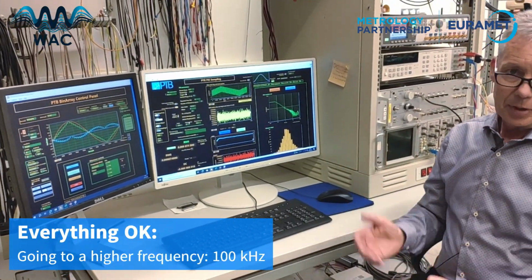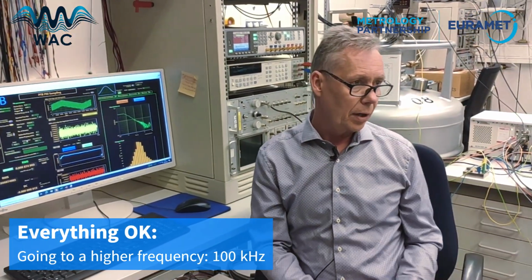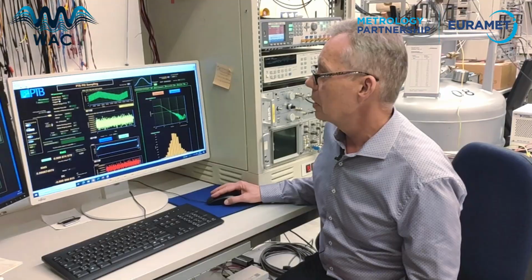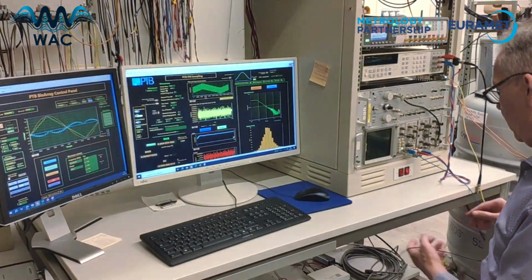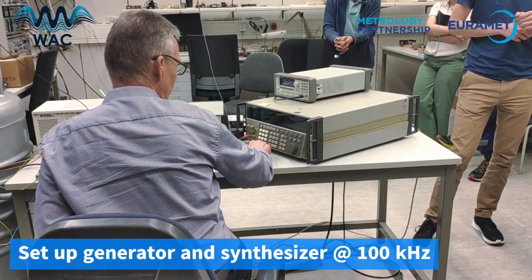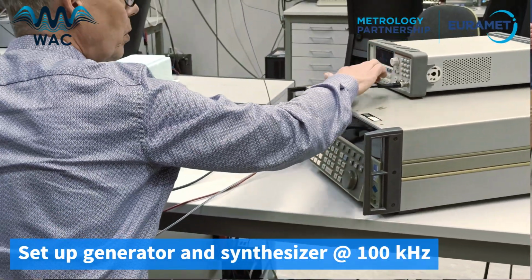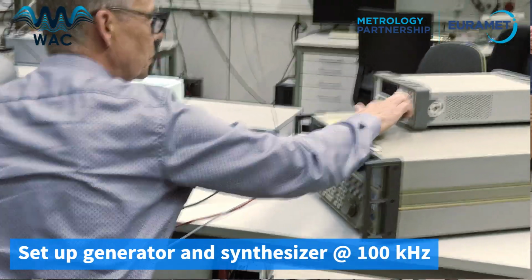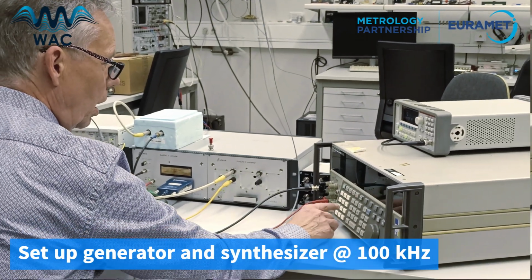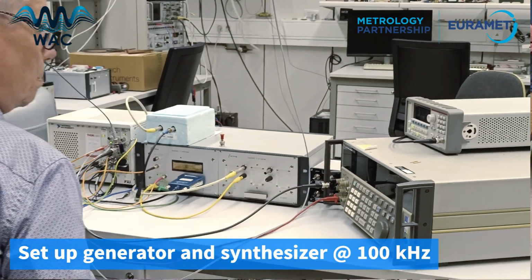Once this is set up, it's very easy now to go to a higher frequency. I just have to reprogram the calibrator to go up to 100 kilohertz, and that's what I do. So I stop this program, I set 100 kilohertz on this calibrator. I also have to reprogram this little synthesizer here to also work at 100 kilohertz. And then I can start and lock the frequency.